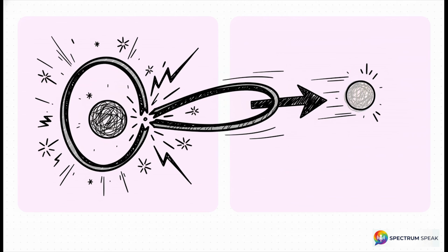If you apply a sufficiently large electric field across a material, the pulling force simply becomes too great. The rubber bands snap. Electrons are literally pulled completely out of their molecular orbits. The material abruptly stops acting like an insulator and instantaneously becomes a conductor. This catastrophic event is what we call dielectric breakdown.